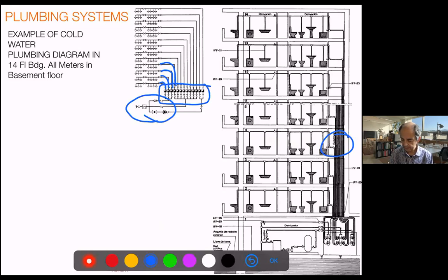And you have always the valves just apart from the counter, and then a new valve at the entrance of the house. See how also it's nice to have a valve at the entrance of each room. So you may cut the kitchen and still use the bathroom. And you should have also a valve before each of the machines. So if you need to repair the sink, you can still use the rest of the appliances. And these valves are usually the spherical, the ball valves.